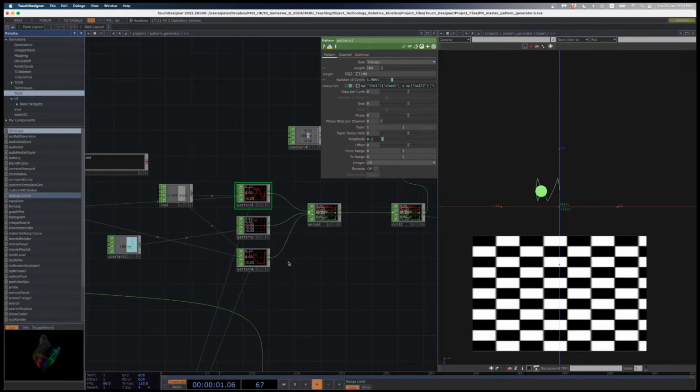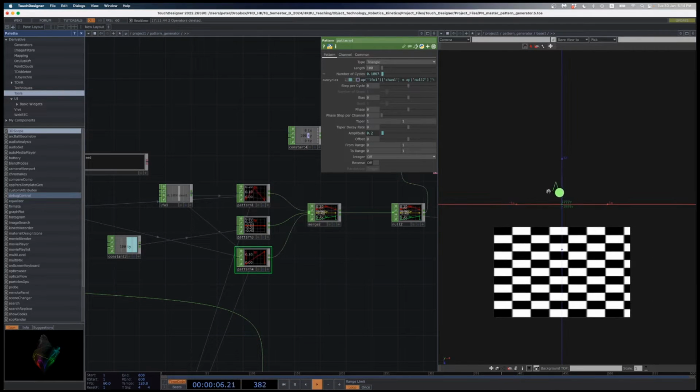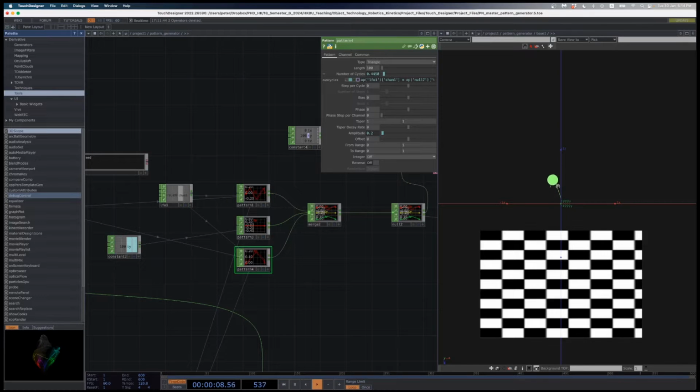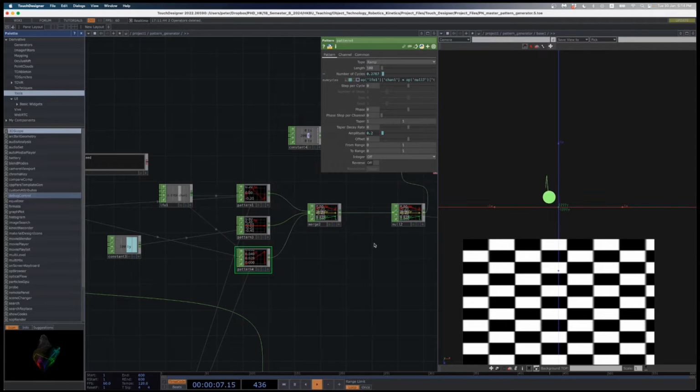The only thing you've got to be careful of here is that if I make both of these a triangle, we want to make sure that our pattern never makes the robot jump quickly to another position. We need to have looped movements because, as you might remember, the robot can't just teleport from one position to another, right? There's a limit to how quickly it can move. So if I go to a ramp or something, I found some combinations that were requiring a bit of a jump in the pattern. Yeah, there we go. See how it gets to the end there? It's not a loop.